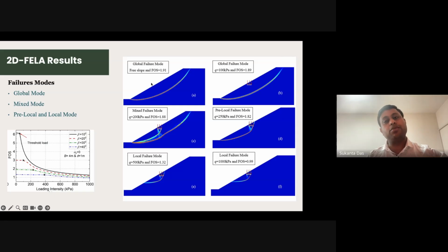That type we call face failure. Then sometimes when the slope fails through the toe, we term it toe failure. And in some cases, the slope consists of totally loose material and debris, heavily susceptible to pore water pressure, and at the bottom you have a highly rigid layer. Then it may slide along the base, so we can call this base failure.